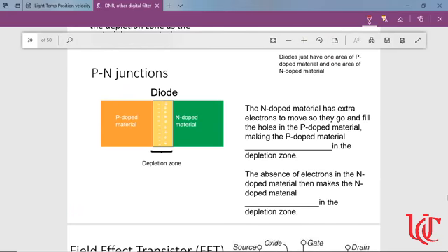When I have those two junctions, p- and n-doped, I again get a depletion zone buildup here. I'll get negative charges on the p, positive charges left on the n. It will only happen for a little tiny region where they're next to each other, because I don't have enough of a draw to pull, let's say, electrons all the way from over here all the way over there. They're only going to move a certain distance, so I only get a little region from it.